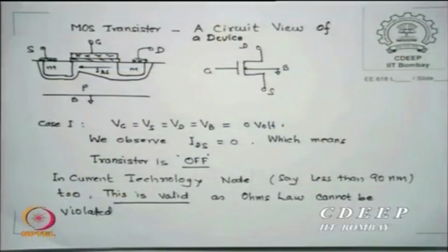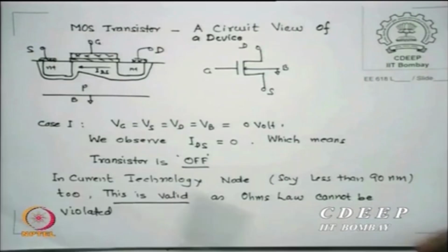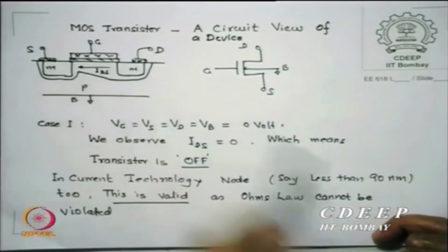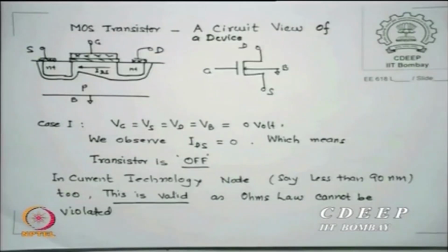Okay. We will not go further down into how technology manages that, maybe that is also relevant someday, if not now at least today, but it is okay. So here is a typical MOS transistor shown to you. This is my substrate, okay, which is p type. So it is an n channel device shown to you. I have two regions diffused or implanted in that, the source and drain, n plus. This is a two dimensional picture, but as I said to you earlier also many times, the MOS transistor is a three dimensional device.